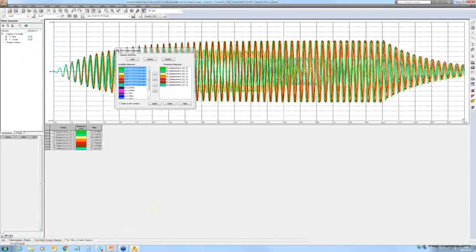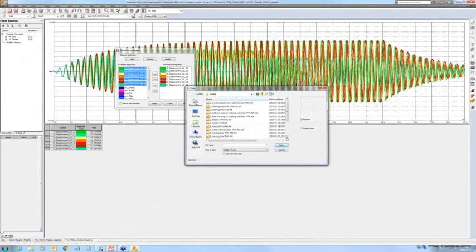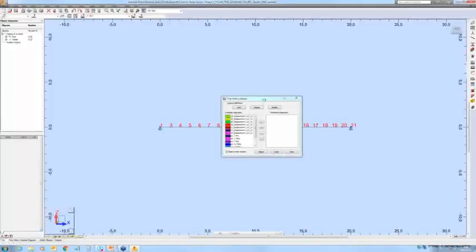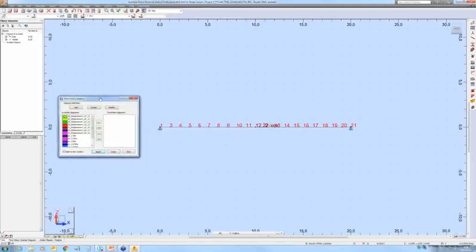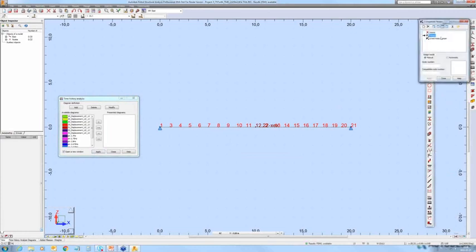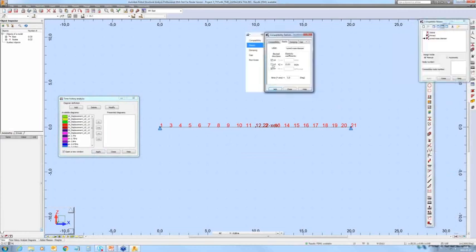Okay, so if I now open the model where I have the damper defined, we'll see the difference this damper makes. But before we look at the results, let me show how the damper was defined. So we have a compatible nodes defined here under the force. And if we go to the definition of compatible nodes, you can see that there is a certain elasticity and certain damping defined